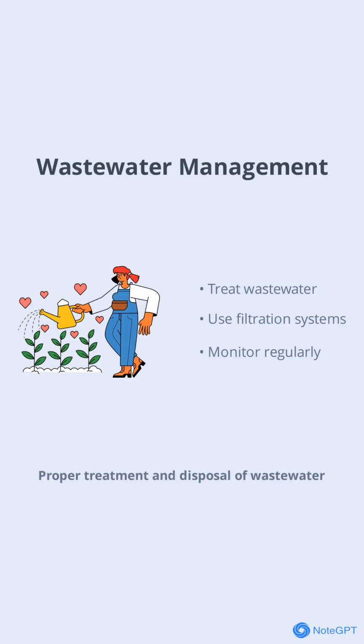Proper treatment and disposal of wastewater is essential to prevent environmental pollution. Construction activities often generate wastewater that may contain sediments or contaminants. Implementing sedimentation tanks, filtration systems, and regular monitoring can help to ensure that wastewater is treated before being released. This protects both the environment and the reputation of the construction project.